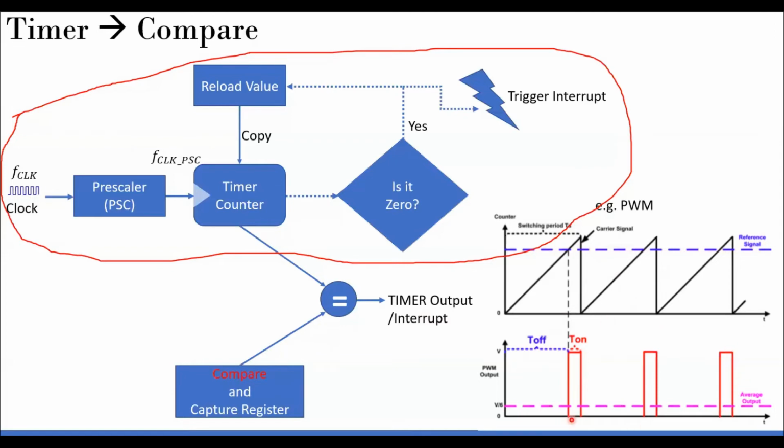The beauty of this curve is that you can use it to control the speed of a motor. So what does the speed of a motor depend upon? Let's say a DC motor, to make it simple. The speed of a motor is directly proportional to the input voltage. So if you give some input like this, a DC motor will treat it as an average DC value. The average value, if I take it, will be this pink shaded line here. So it's a low value.